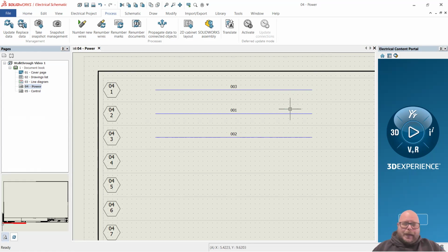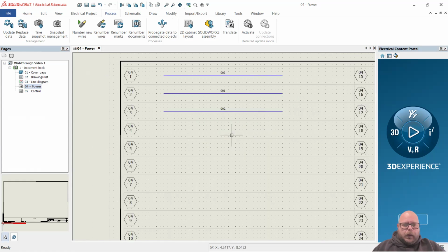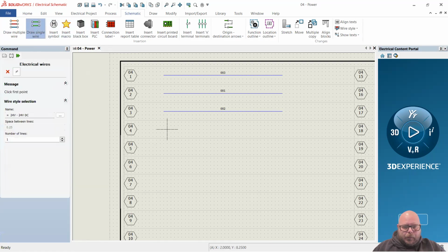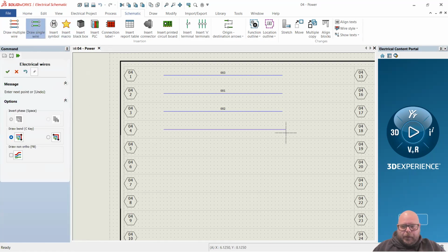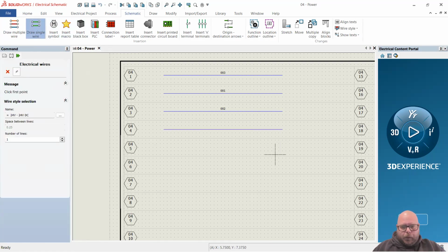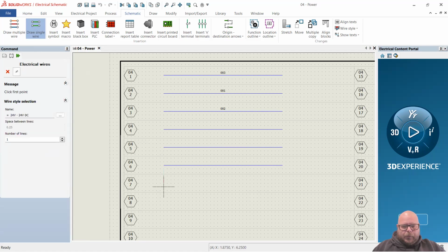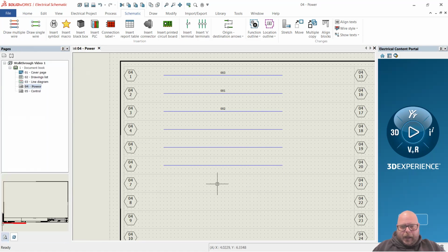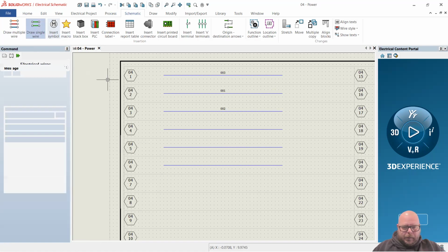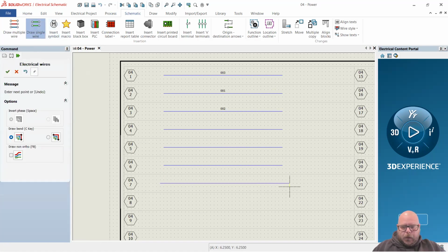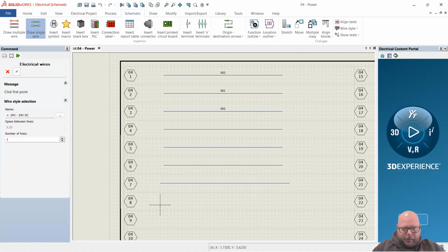But what that did is it's now in three characters, so it has leading zeros. Let's draw a whole bunch of them. Let's get up to 10 just to show that the leading zeros go away, because that formula now is basically calculating whatever the wire number is, make it take up three spaces. And that's a trick we're going to use, because I like it to always have four spaces when I actually get my formula in there.